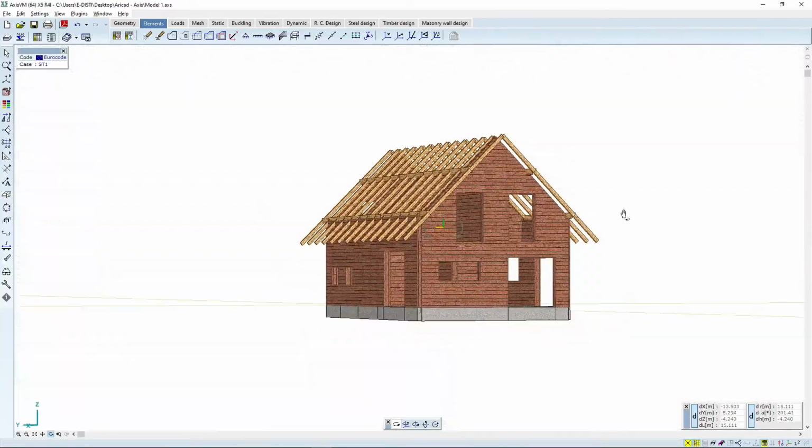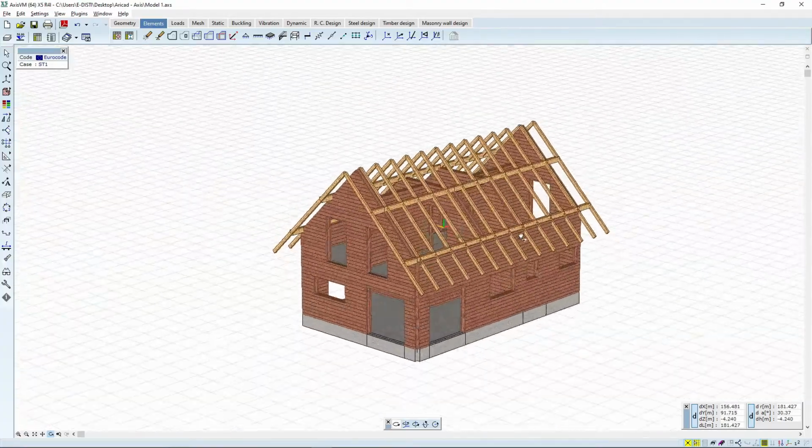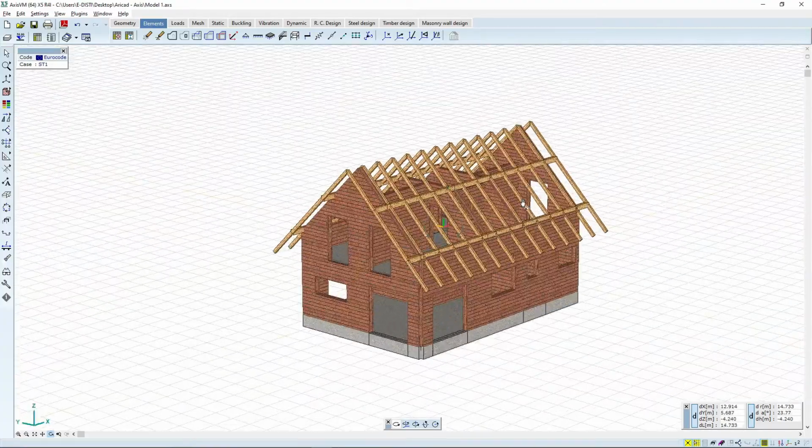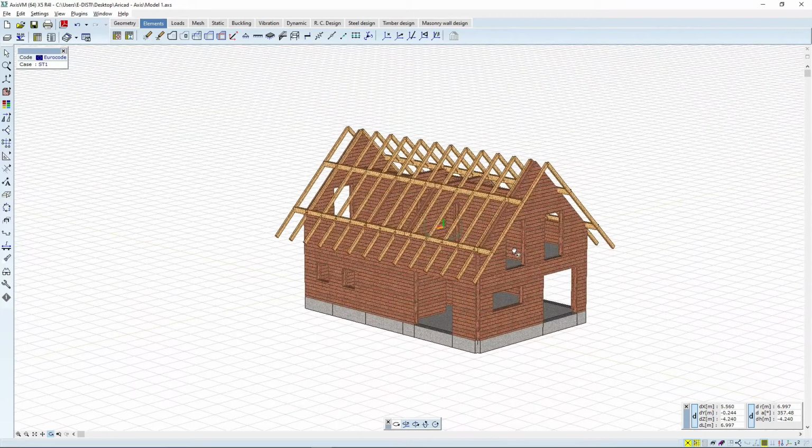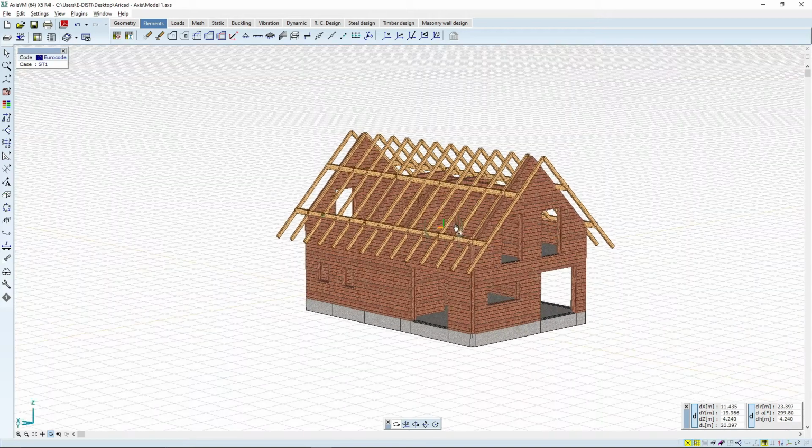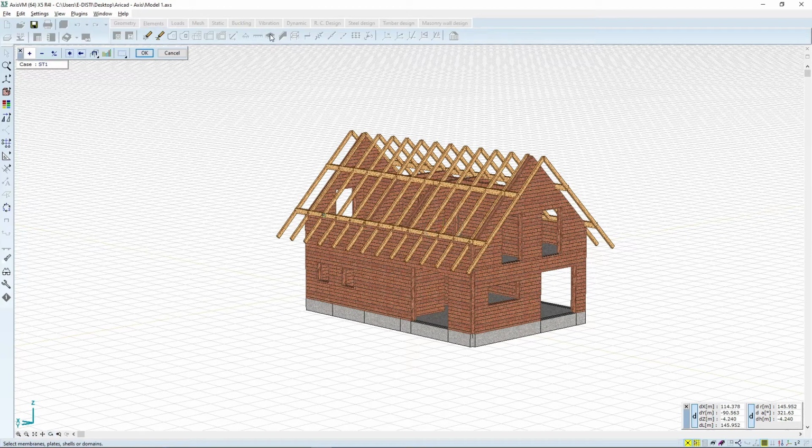As you see, we only have the structural elements. Okay, when we have done this, we can now start adding loads to the model. So we go under the load section. Just one more thing before we start adding loads, we must also define the support. So we are going to add a big surface support at the bottom.